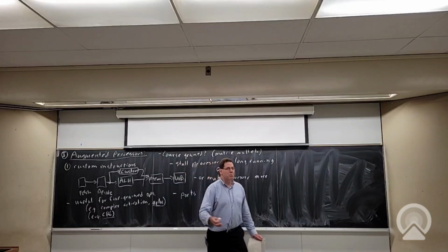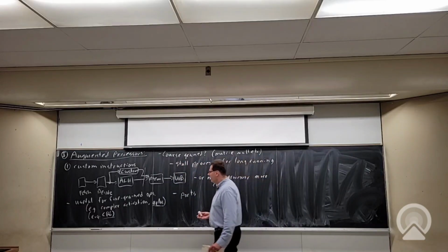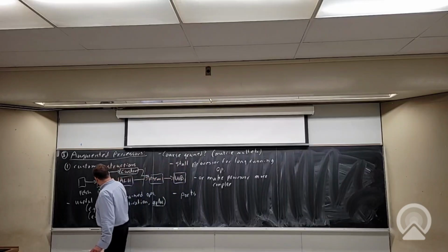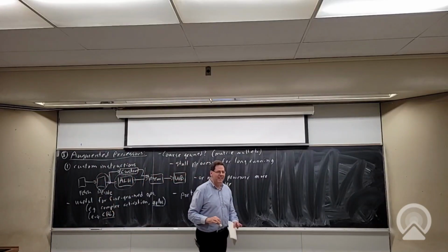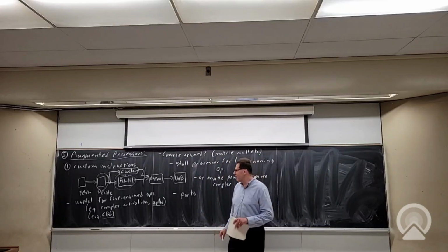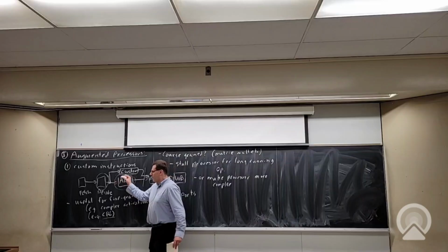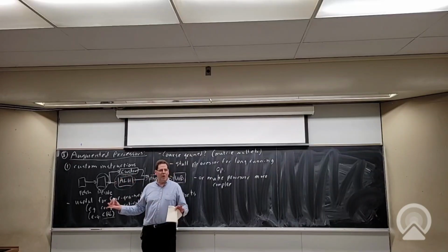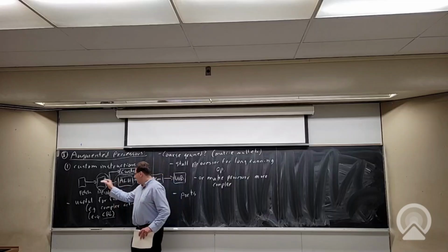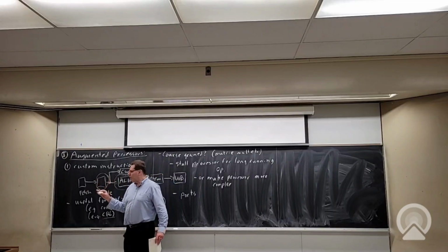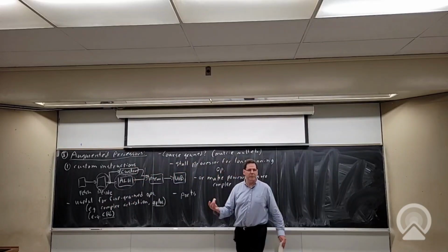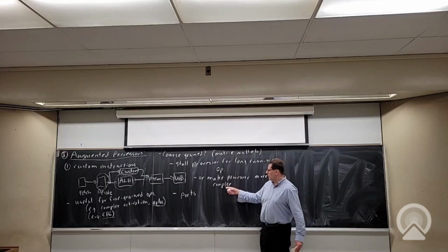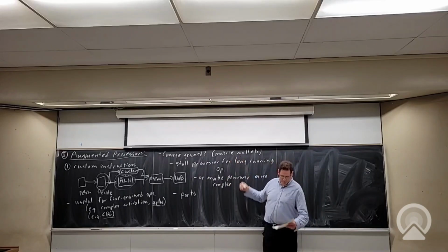You could make more ports to the register file, right? This is where we're actually reading the register file, somewhere in between these 2 phases. I didn't actually put an RF in this, but somewhere in there we're reading the register file. If I want to get a lot more data from the register file, I have to make my register file a lot more complicated. And that basically is not going to fit the rest of the processor very well. So they just don't allow it. They're like, no, you're hooking into the processor, you're a custom instruction, you get your 2 pieces of data. And it basically just doesn't really work for something coarse-grained like matrix multiply very well at all.